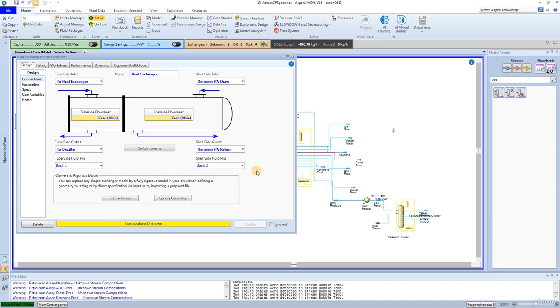The flow sheet will then need to resolve with the new heat exchanger output. This scheme will introduce an iterative calculation, which can be facilitated by adding a recycle logical operation. This concludes task 3.